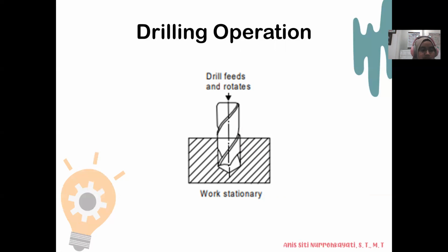A suitable drill is held in the drill machine, and the machine is adjusted to operate at the correct cutting speed. The drill machine is started and the drill starts rotating. Cutting fluid is made to flow liberally and the cut is started. So if we operate the drill, we must use oil to lubricate the drill and the workpiece.